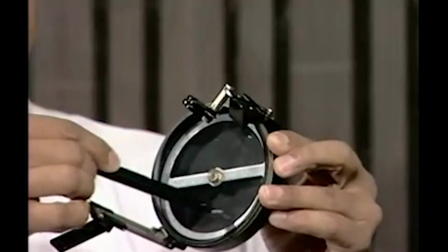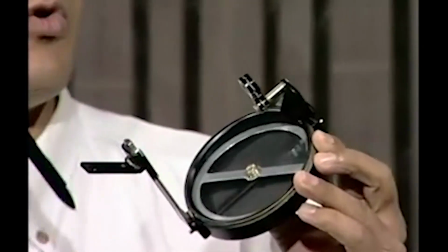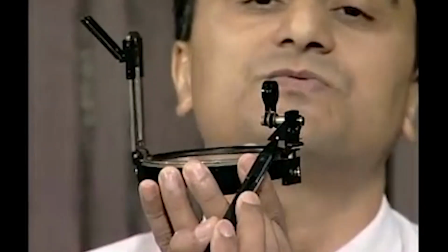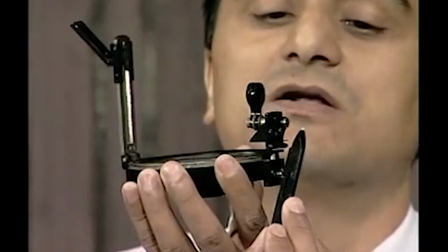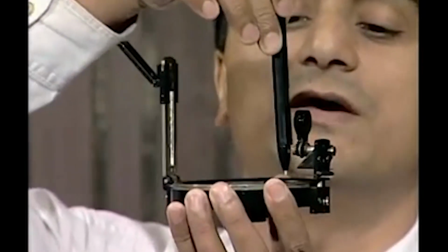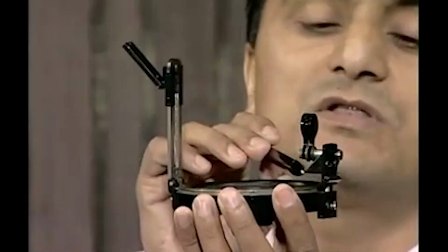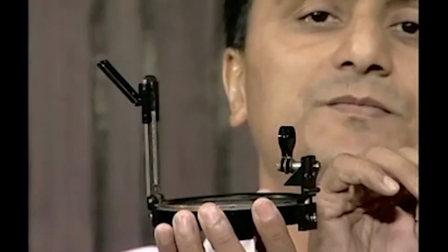Now over here, if I show it this way, we have a measuring circle or the graduated circle. We will see the specification of this in a moment. Nonetheless, along with this vane is fitted a prism. My eye is kept on this side, and the graduations are written down there. So what is the role of the prism? The prism will take these graduations and reflect them here.